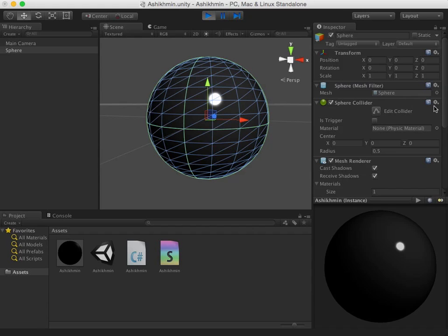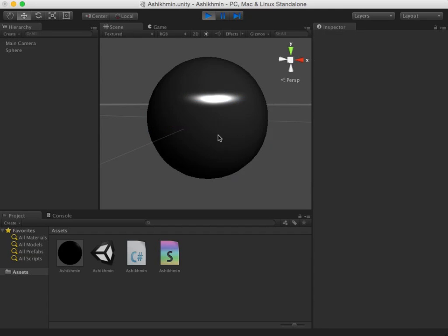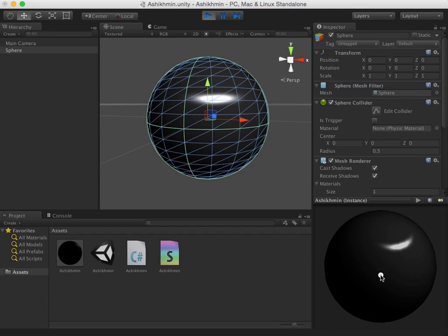So the trick then, if we want to make it have an anisotropic specular property, is you just make them unequal to each other. If I make that 50 in y, we suddenly end up with the specular lobe moving around. As you can see, when I move the sphere, as I showed before, it deforms with respect to the surface tangent bases on the sphere.